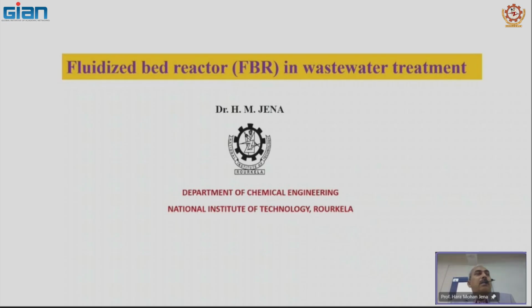So in the fluidized bed, the suspended solid particles are of relatively smaller size, maybe 1 millimeter to 6 millimeter particle size in a three-phase fluidized bed. Smaller particle size gives a high surface area for the same bed mass of solid particles compared to a packed bed.